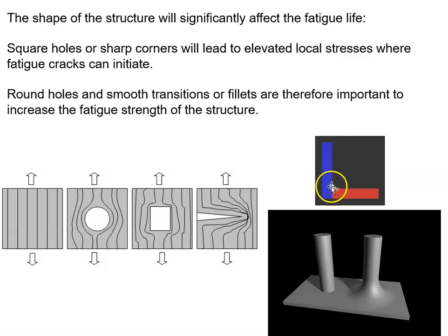The two pieces are being joined there, and that smooth surface helps to reduce the stresses. Same way, we could just weld this cylinder to this with an abrupt change in geometry, but that would lead to increased stresses, where this is filleted and it decreases the level of those stresses.